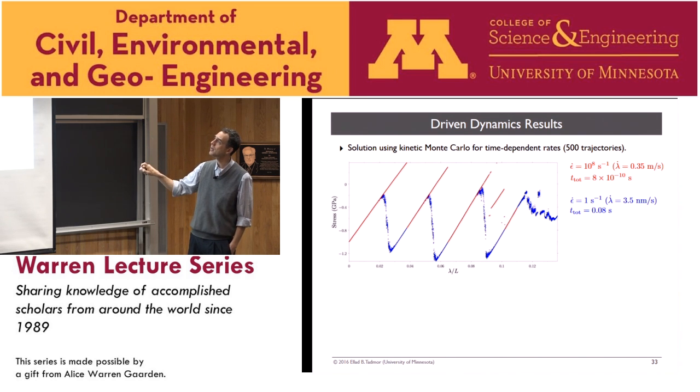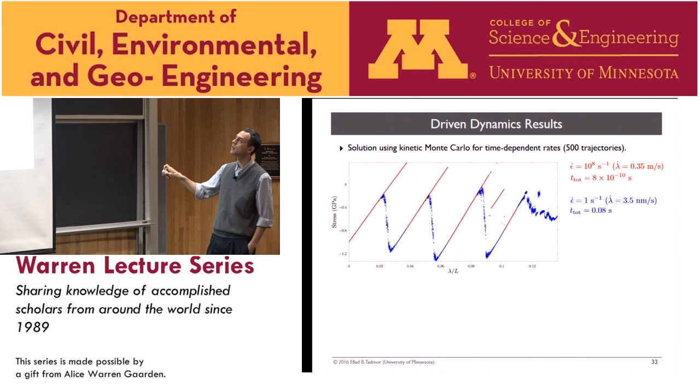In the high strain rate, what happens is your system basically gets stuck in whatever basin it's in because it doesn't have time to escape before you already reach the instability. Remember, if I just keep pushing long enough, it eventually just folds over and loses stability. But if you give it temperature, it could hop out. But if you load so rapidly that it doesn't have time to do that, it doesn't happen. And so you get the red curve.